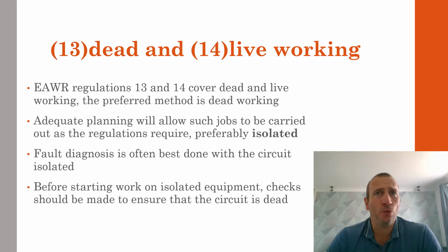In Regulation 14, where we're talking about working near live conductors, it states that live work should not happen unless it is, first of all, unreasonable to be made dead. Secondly, it's reasonable to be working near live conductors. And finally, that suitable precautions have been taken to prevent injury. In simple terms, don't work live unless you have reasonable precautions in place.